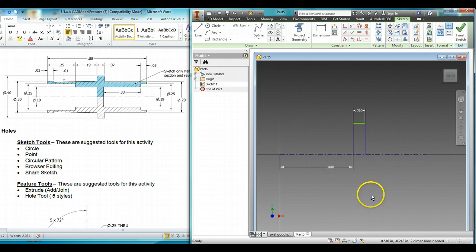Take those to the solid line and click off that center line so it stops happening. Okay, so I know that you'll see this feature right here and you'll go, wait a second, that's not right. You're right, we're going to take care of that a little bit later on towards the end of this actual drawing. Now I am going to locate 3 horizontal lines here.